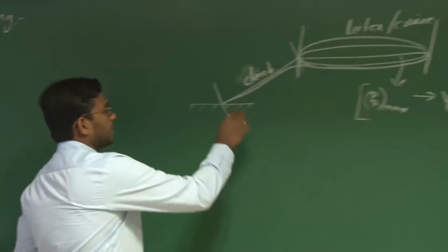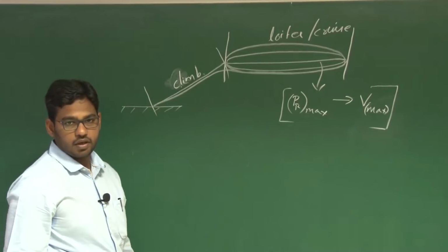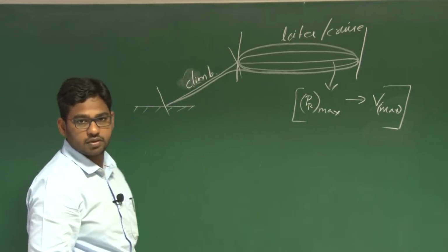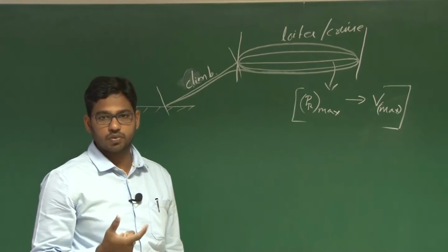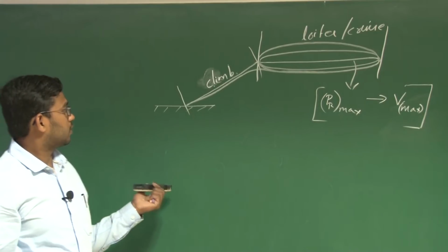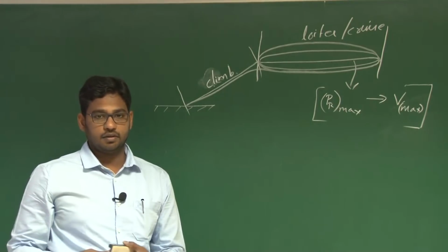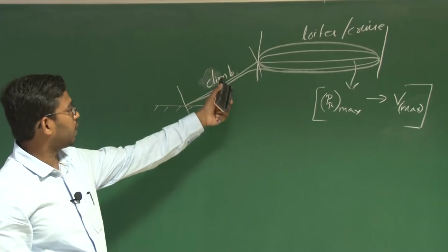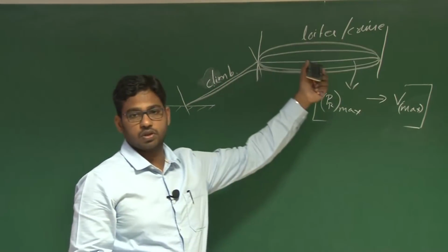So we should also understand the requirement of this climb phase. At the same time, we should know how this power requirement changes during the climb phase and what parameters it depends upon, so that you can correspondingly select the engine, right. Finally, whatever engine you select should satisfy the requirement of the climb as well as the cruise phase.